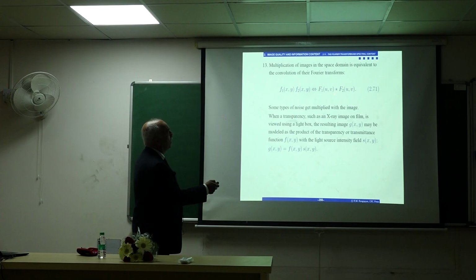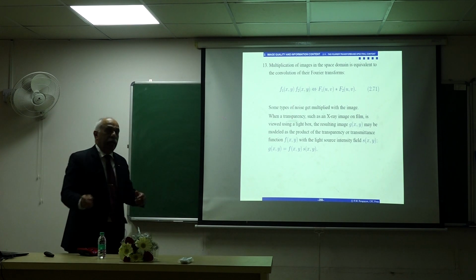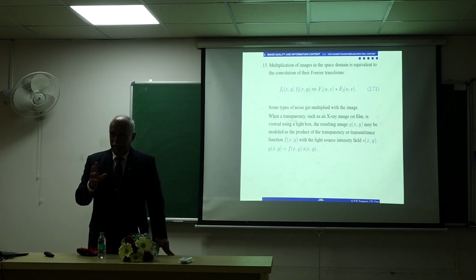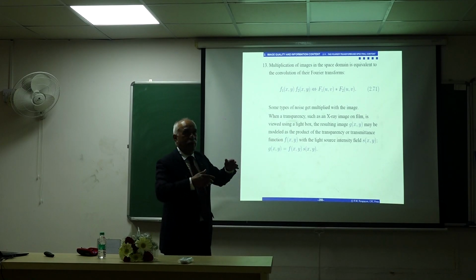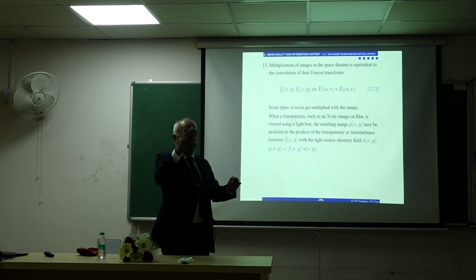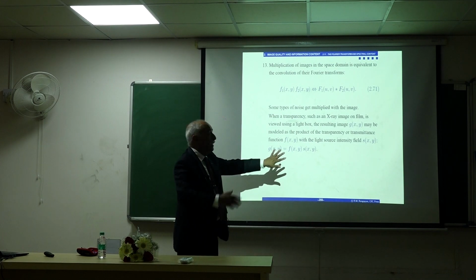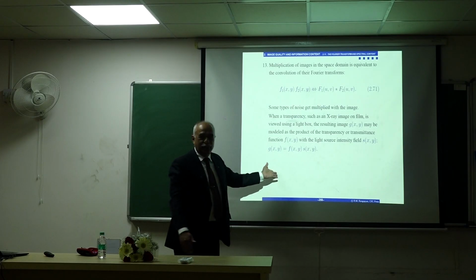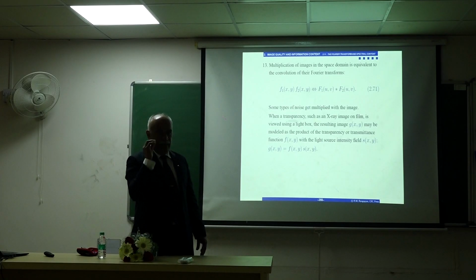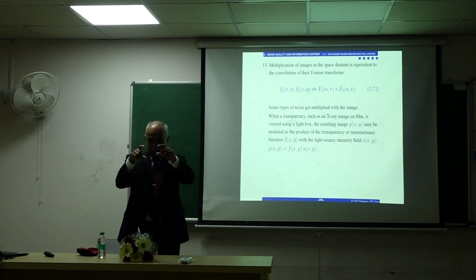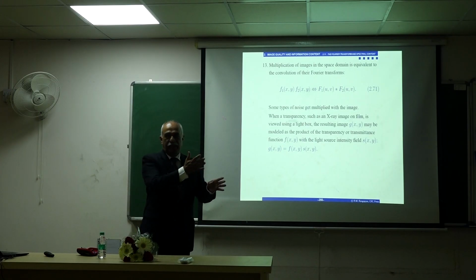Multiplication of images leads to convolution of their Fourier spectra. Convolution leads to multiplication. Multiplication leads to convolution in the other domain. In time domain signals, it is not common to encounter multiplication. You encounter addition of signals and convolution. But in images, it is possible. What you're seeing here is a multiplication of an illumination pattern of the lamp there. It is transmitted through some sort of, let's call it transparency with these letters, and that is projected. So if I put this, then that is multiplied with the transmittivity of this, which is 0, so you get my shadow. So the image you see, or record, is a product of the illumination function, the light field, with the reflectivity, if I take a picture using a camera, reflectivity of whatever the pattern here is, or transmittivity if I'm sending it through film or some transparency.